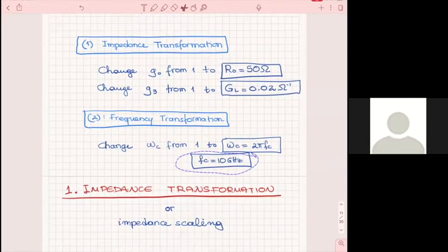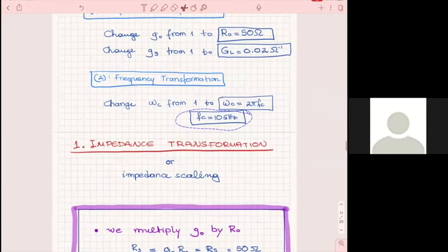So now I remember, the shunt, because I noticed that some people had difficulty with that in the midterm. What shunt means is in parallel. You see here that you have inductors in series and capacitors in parallel, so in shunt configurations. From there, we have to do two things: incorporate the impedance values we would like to see in the filter, and also incorporate the real frequency we want to see. Because now, remember, in the prototype, omega sub c is 1.